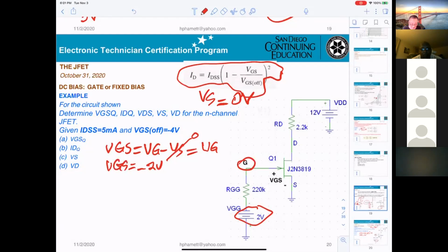Mr. Pham, I'm a little bit lost. Okay, VGS equals VG minus VS, and since VS is equal to 0, it's equal to VG then, okay? Right. I follow that. But then how do we get, I mean, is VG equal to minus 2 volt?